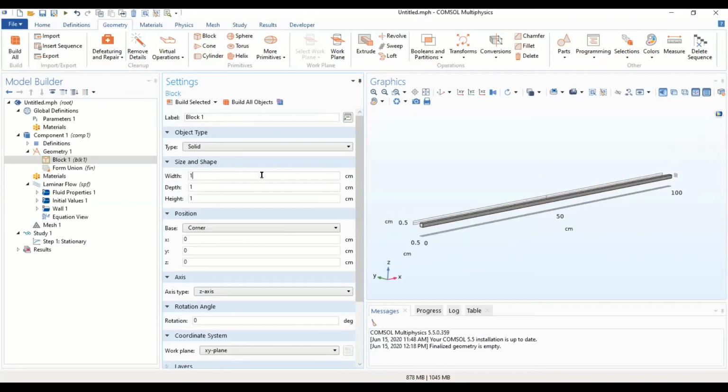You can type your units in any system, empirical or British, SI or any other unit system. As long as you have the units between square brackets, it can be translated or converted into COMSOL by itself. You don't have to convert every single unit. You can have part of it in SI, part of it in British units, and then it can all be converted internally.